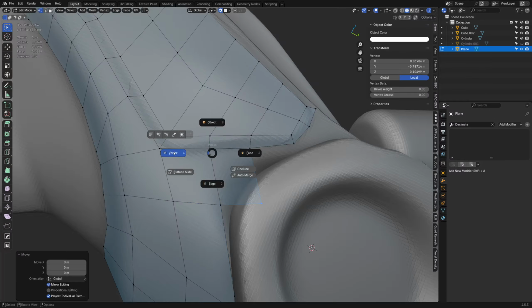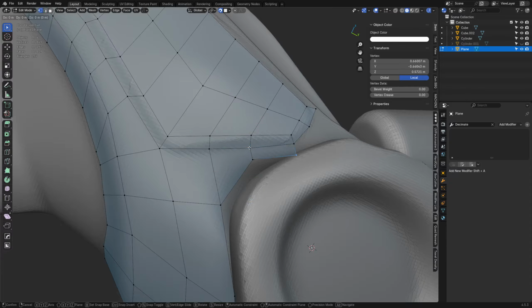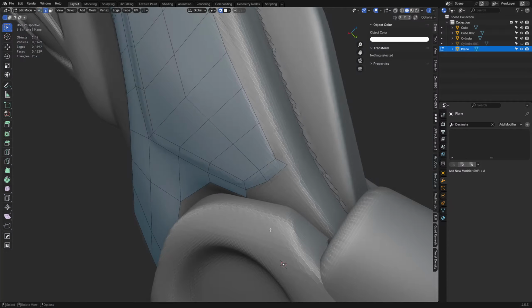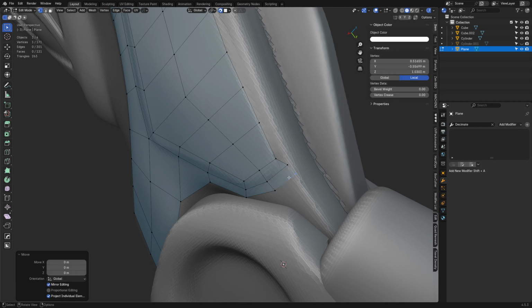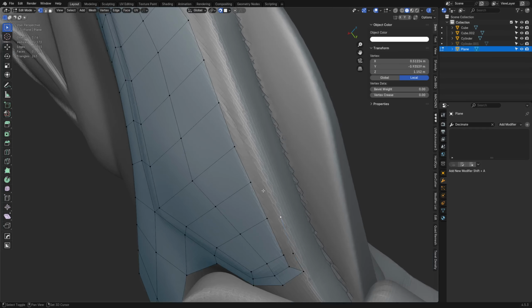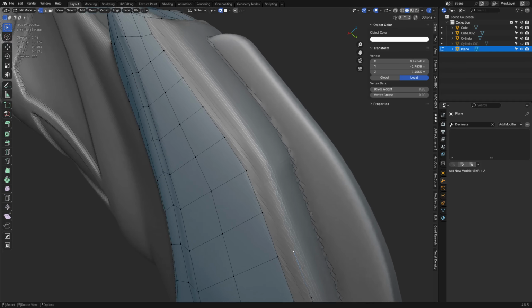This we can F2. This one we're going to dip like that. I'm not going to think about it too heavily anyways. This will teach you to subdivision model as well. Like if you're not very good at it and you start trying to retopo things, you'll get better at it, basically. Kind of how it works out anyways. That's a good thing. It's usually what you want to do. You can also Control right-click vertices. Or edges or faces, I think even.